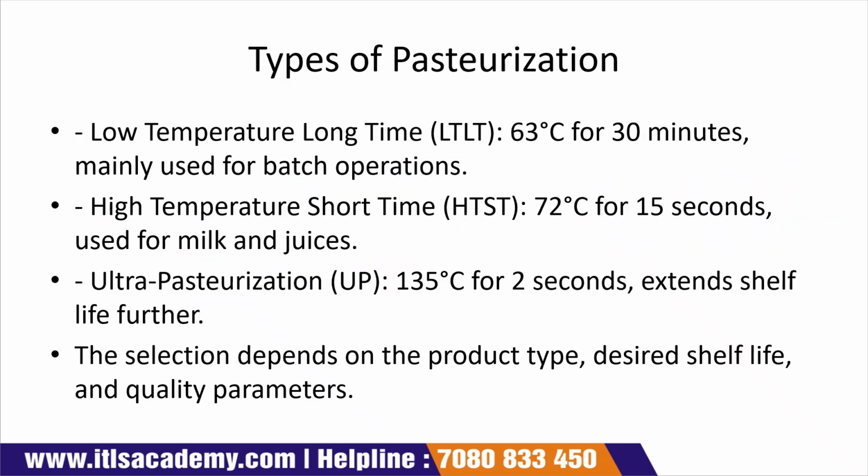Next, pasteurization can be divided into three categories. The first one is LTLT, known as low temperature long time. The second one is HTST, that is high temperature short time, and the third one is UP, that is ultra pasteurization.